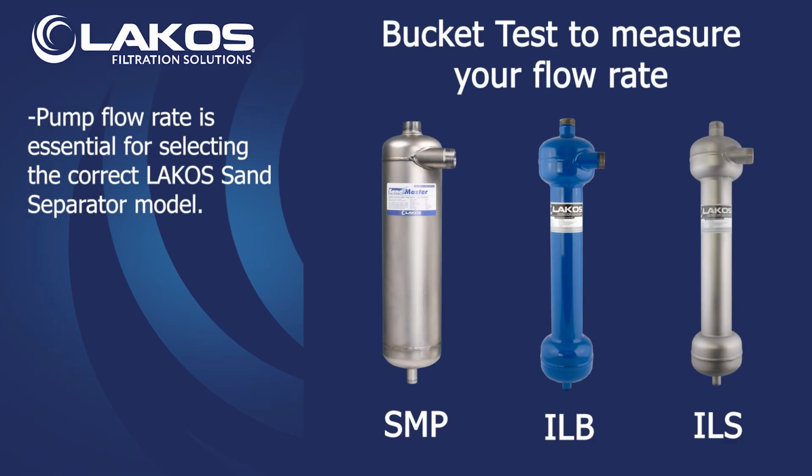Before you select a LAKOS sand separator for your residential well water, it's important to know one critical number: your pump's flow rate. Flow rate determines which separator model will work correctly with your pump and plumbing system. If the flow is too low for the separator, it won't generate the proper internal vortex to remove sand. If it's too high, you risk system pressure loss or equipment damage.